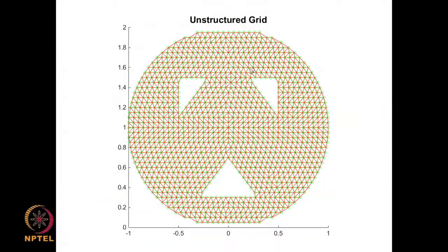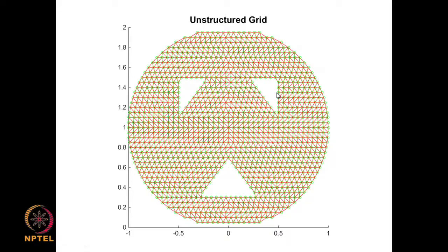So, at the end of this you have identified all the nodes of all these meshes. So, from these you can go ahead and find the areas and volumes and the surface orientations, all those things that you need for a finite volume analysis can be done with this. So, one could do a heat transfer problem in a domain like this with different boundary conditions applied here and here, here, here, and one could generate the temperature contours in this. So, that kind of problem can be done using the unstructured grid method.